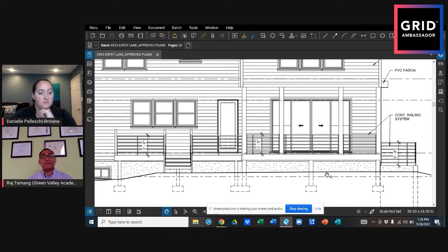So this is what happens. If you have 30 inches and you don't have a railing, safety-wise, if you have little kids, I would be concerned, right? I would probably still put a railing. But sure, yeah, I think a lot of people probably still would put a railing. You're just not required to. Correct. But if it is less than like 12 inches or so, I don't think you have to.